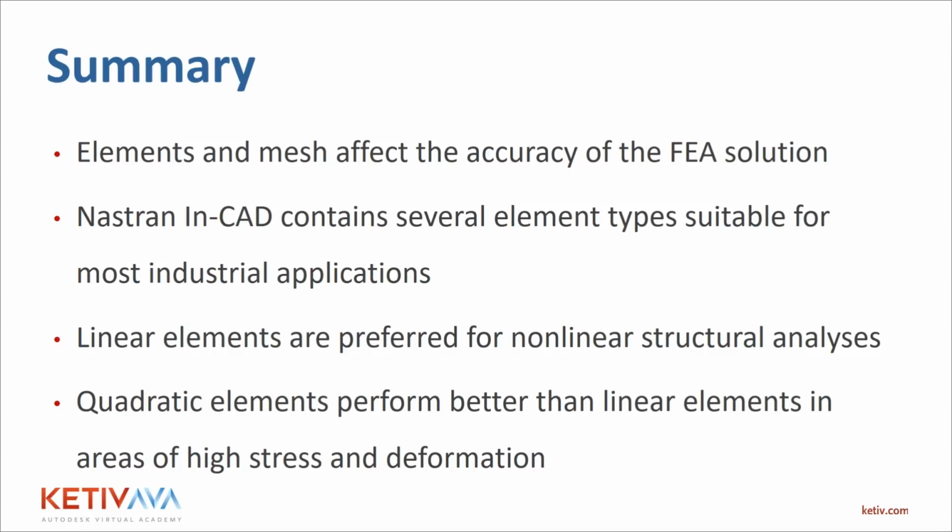Now, just a couple of things to keep in mind if you are using elements already and running analyses. You want to make sure you use linear order elements for non-linear structural analyses. I know that's a little hard to remember, but try to keep this in mind when you're running non-linear analyses, because most of the time you're likely to obtain more accurate solutions with a fine mesh of linear elements than with a coarse quadratic mesh, even though the quadratic element is presumably supposed to be much more robust and much more powerful. It's useful for certain applications, but not for nonlinear structural analyses.